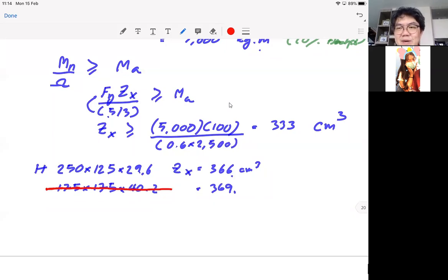In terms of numbers it's not wrong, but nobody uses it. You'll be a laughing stock behind your back because you used an improper section. So don't use a column section for a beam. It's just not very engineering at all, even though your structure will be fine.